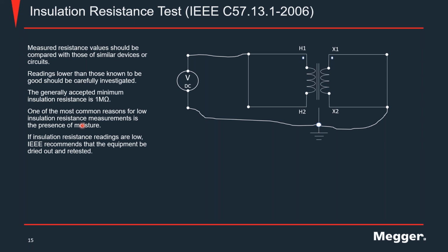Now, when you're doing the insulation resistance test on the CT, you're not only testing the insulation resistance on the CT, but you're testing the insulation resistance of all the wires that you have connected to the CT.